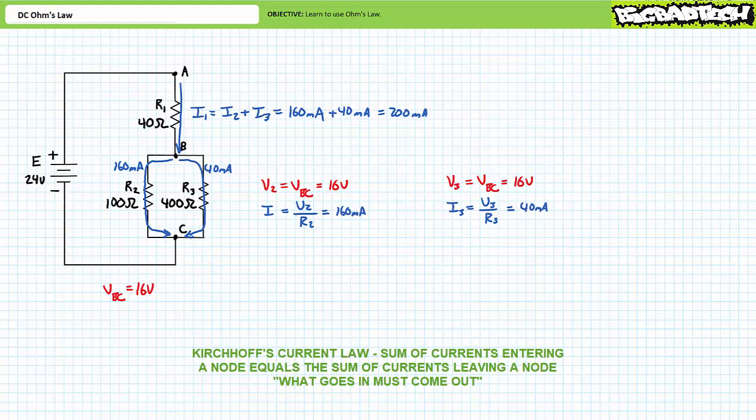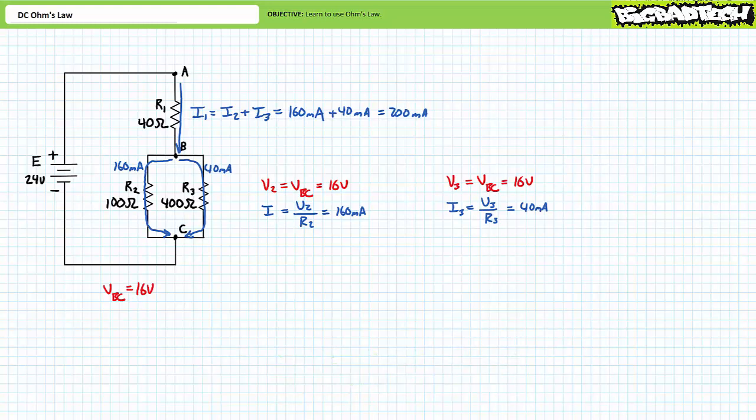We'll examine Kirchhoff's current law in greater detail in later lectures on fundamental parallel circuit properties. In short, what goes in must come out. Through this application of Kirchhoff's current law, we now have an additional data point concerning resistor R1. We now know the current through resistor R1, I1, must be 200 milliamperes. We know current and we know resistance. Voltage is equal to current times resistance.